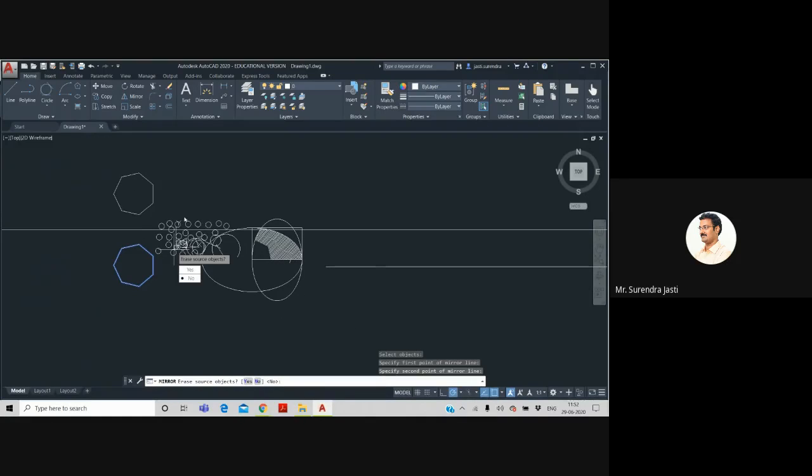And actually you are not seeing much difference, so let us do it with another object drawn with a polyline. Suppose I want to mirror this object. Mirror, pick the object. This is the advantage of drawing with a polyline. If you want to mirror all these lines, simply selecting once, I can directly do the mirror.